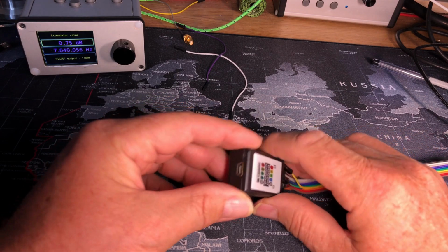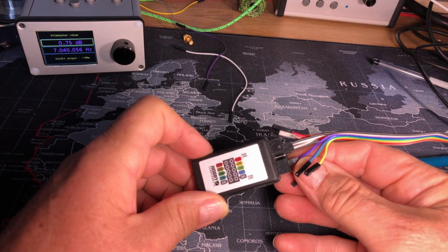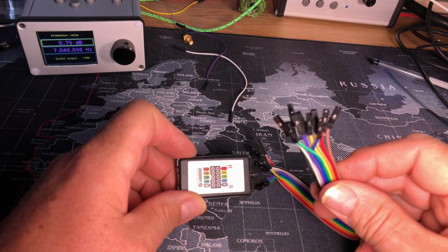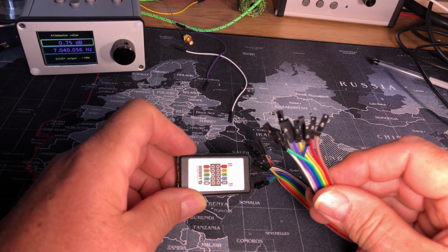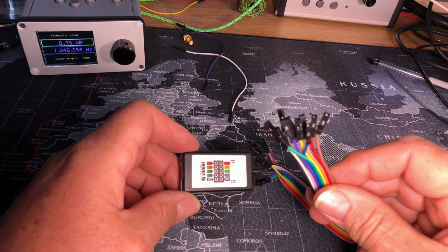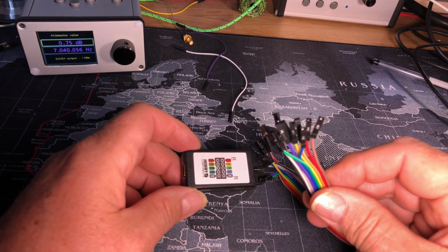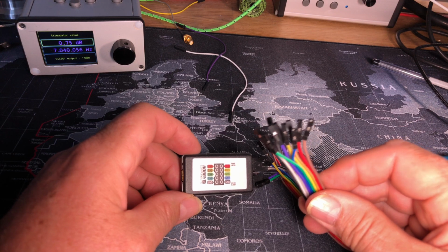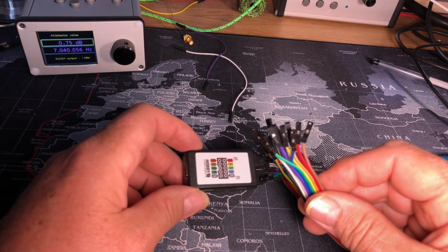With this connected to the computer and wired up to the header on the back of the Simple VFO hardware, I'll be able to analyse the clock signals and the clock train on the computer and double check to see if the software is working correctly before I hook it all up to my digital attenuator breadboard.